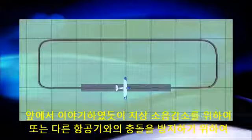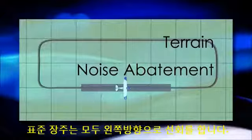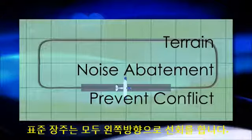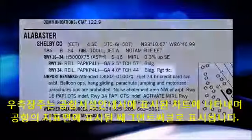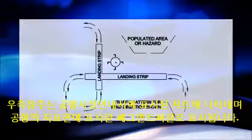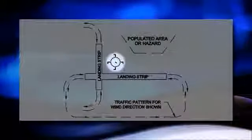As previously stated, standard patterns are flown with all turns to the left. For reasons of terrain, noise abatement, or to prevent conflict with other operations, some airports have right-hand patterns for some of their runways. Right-hand patterns are depicted on aeronautical charts, noted in airport facility directories, and shown by indicators on the surface of the airport referred to as segmented circles.